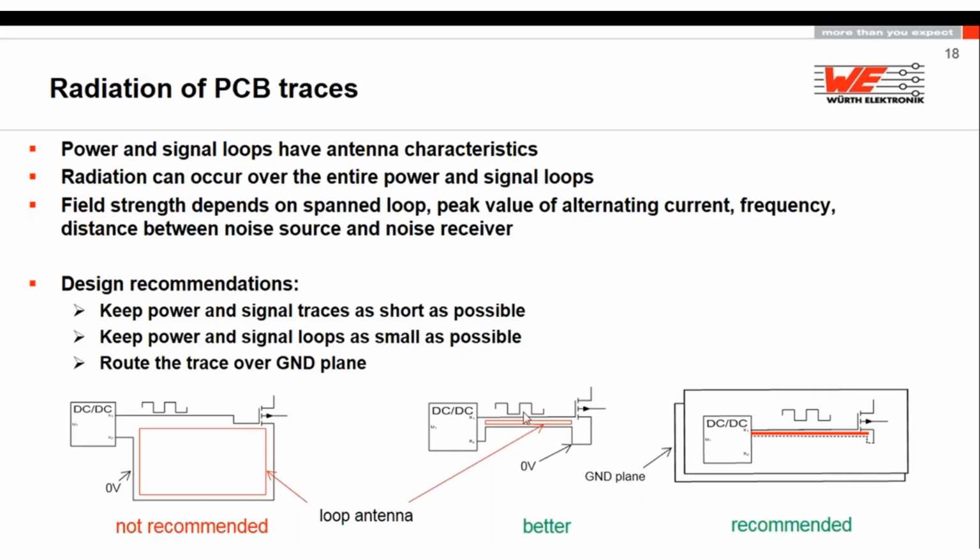And the best thing that you can do is make a kind of PCB track matching, antenna matching on PCB level, so that you have the same length and the same distance, to have the same impedance between the MOSFET and the controller. Then you can do a good thing. I like to do that in two layers: I put a track on the top layer from controller to the MOSFET. On the bottom layer, I make an additional path, not just by accident where the current comes back. I make a direct path back to the controller from the MOSFET to be sure that this digital signal is running this way. And then you have fewer problems, especially at high frequencies.